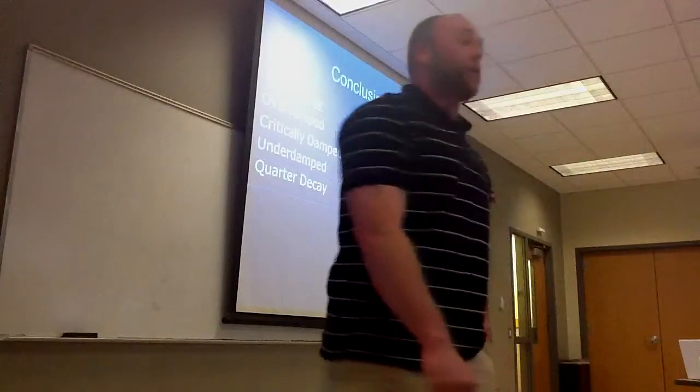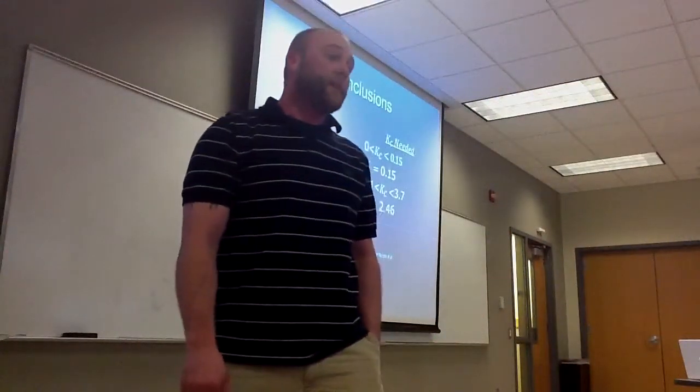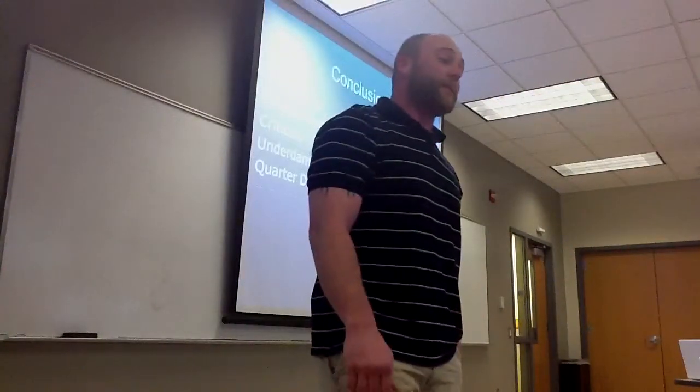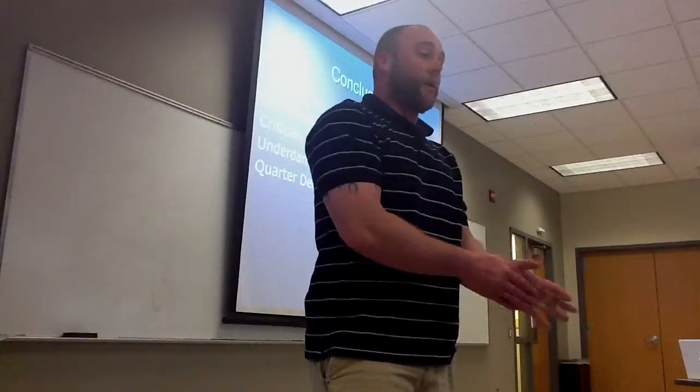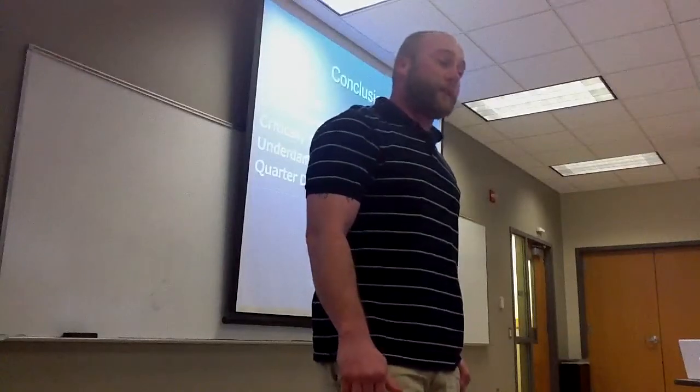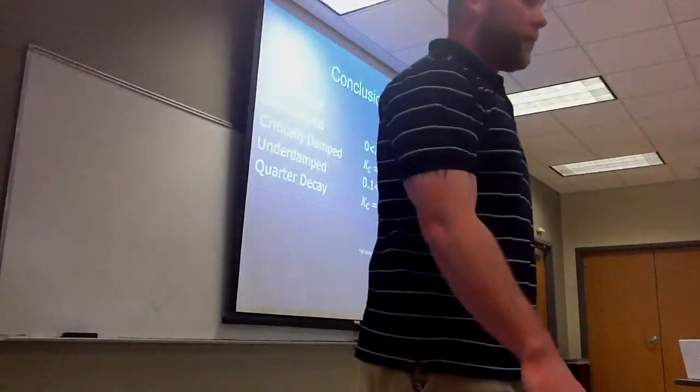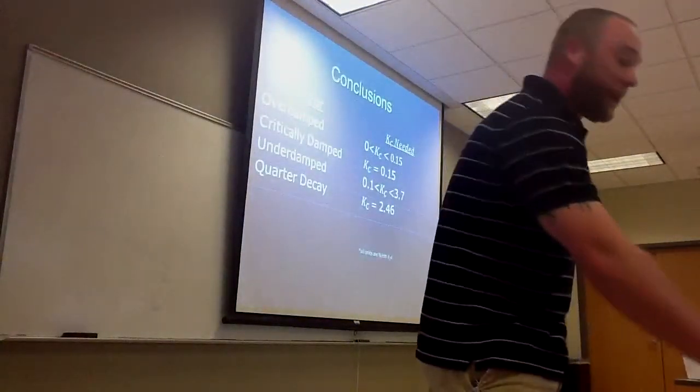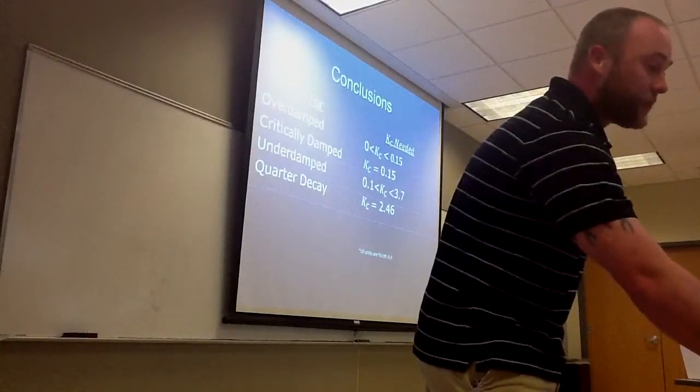And so for our conclusion, the KC we will need for overdamped needs to be between 0 and 0.15. Critical needs to equal 0.15. Underdamped, KC between 0.1 and 3.7. And quarter decay, KC equals 2.46.